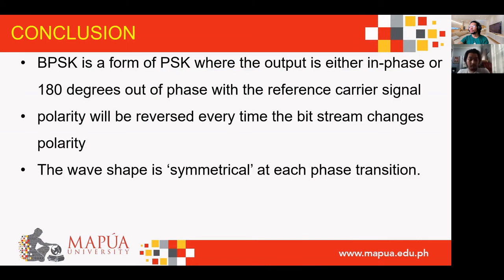Binary phase shift keying is the most straightforward type of PSK, where binary refers to the use of two phase offsets, logic high or logic low. Then a BPSK demodulator circuit consists primarily of two function blocks, a multiplier and an integrator. These two components produce a signal that corresponds to the original binary data. It is an important difference between analog demodulation and digital demodulation.